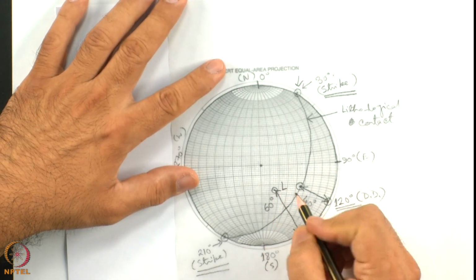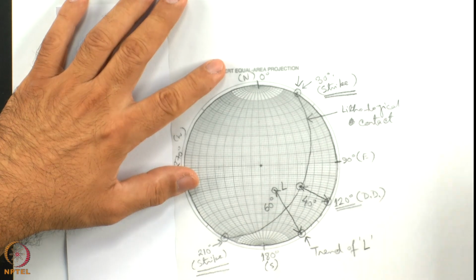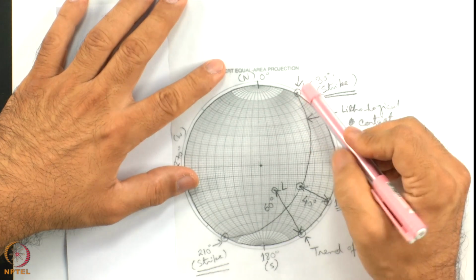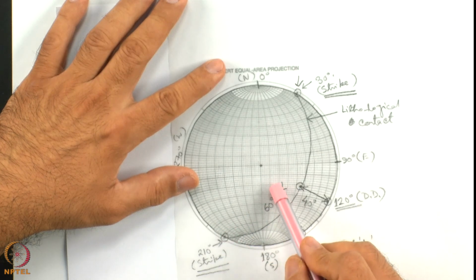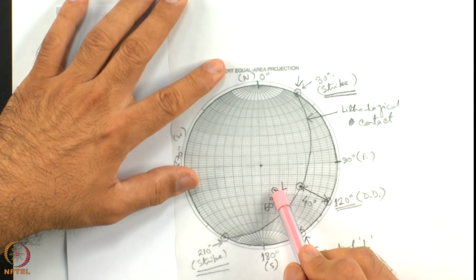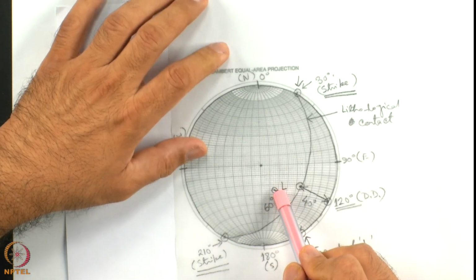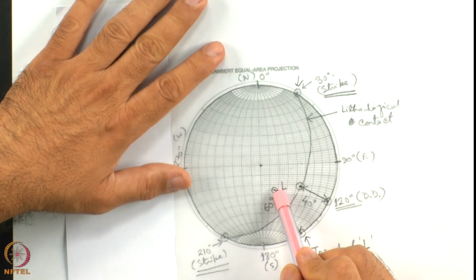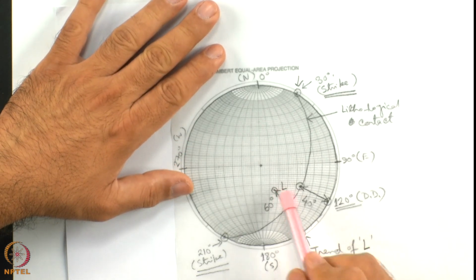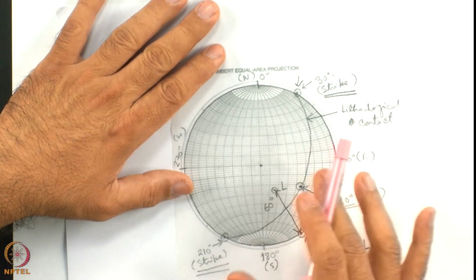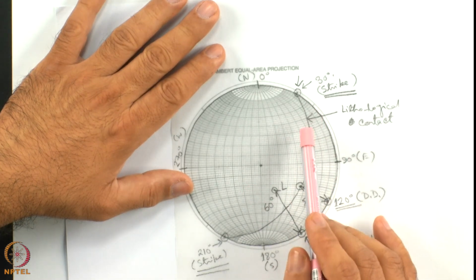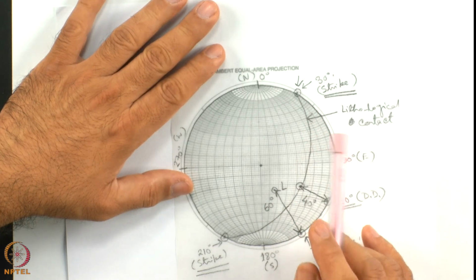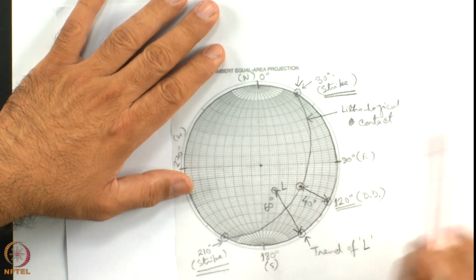So, here is the line. So, what we have got? We have got the great circle representing lithological contact, and the line along which the thickness has been measured. The thickness data is given, and it is not required either to think that we will plot the thickness in the Stereonet. That is not possible. In the tracing sheet, we can plot planes and lines, but the thickness data cannot be brought over here.